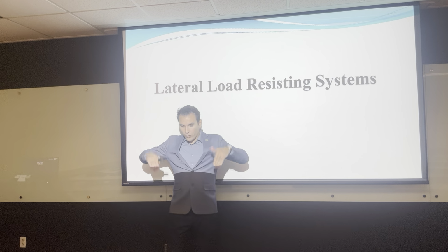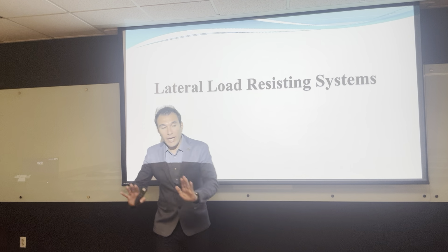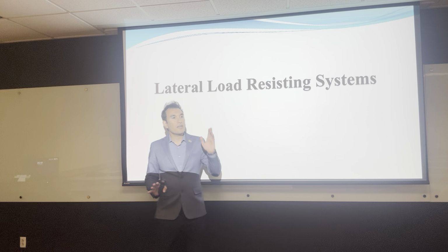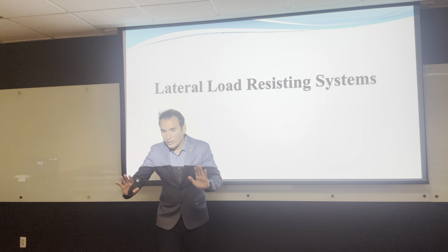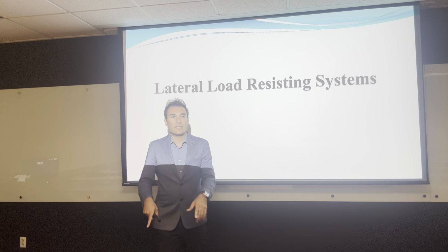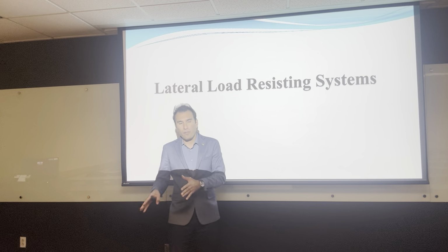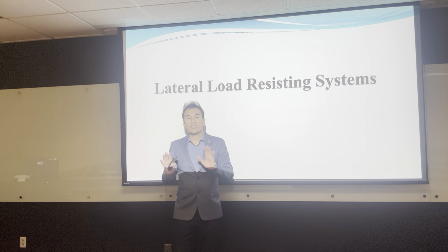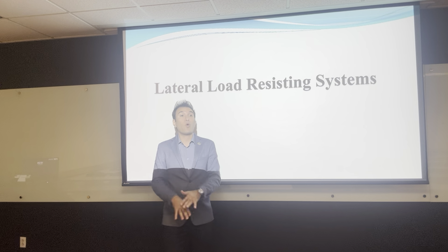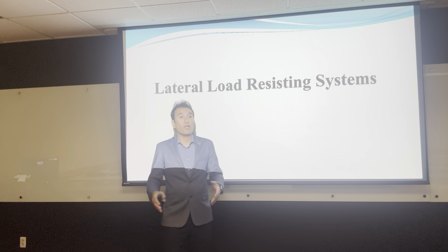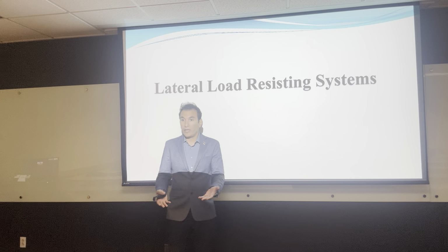But gravity is going this way, and when you have a lateral load, that means there's another system that can resist the lateral load. If you are pushing the building this way, it doesn't matter much what slab system you have. It matters a little bit, but it doesn't matter much whether it's a solid slab or flat slab. They are all masses. They are all loads on the structure, okay?